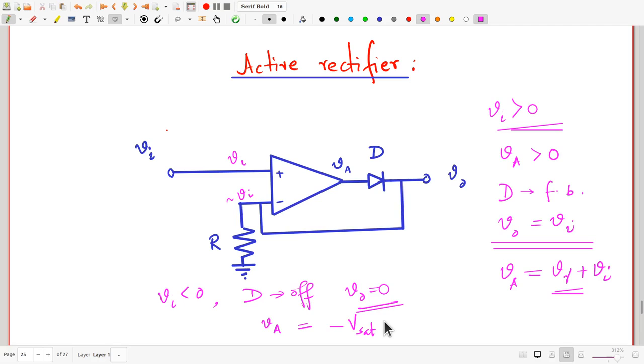Of course, the slew rate varies from op-amp to op-amp and depends on which kind of op-amp you're using. So, the ordinary kind of op-amp that you can buy off the market, the cheap version, let's say the 741 IC, which is the popular common op-amp that is used in labs all over the world, has a slew rate of around 0.5 volts per microsecond. So it takes a microsecond for the op-amp's output to change by half a volt.